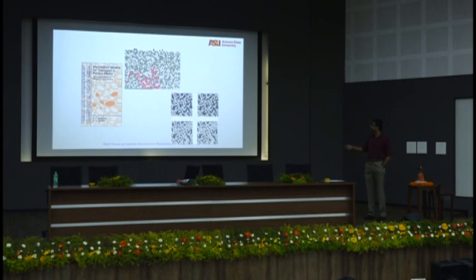This is what you have when you mix cement and water. Right? You have a lot of particles in a lot of water. Which means when you start off hydration, assume that cement hydration is happening in an ocean, and if I have a boat when I start, when the cement is mixed with water, from one end of the hydrating volume to the other end, I can completely go through water, right? Without touching any of those islands.